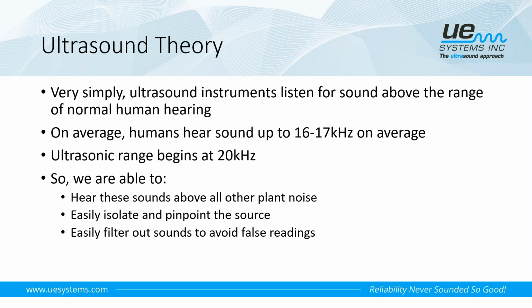And understanding the physics of sound and how sound waves travel will help you to make better use of your ultrasound tool. One of the things that we always stress and teach is the fact that high frequency sound has a tendency to bounce and reflect off of solid surfaces. So if we're pointing the instrument at the floor, for instance, and we're hearing the sound of an air leak, we know that can't be correct because there's no compressed air lines on the floor. So we lower that sensitivity, and that is a way to, again, narrow down the field of view to help block out and filter out those types of sounds to where we can avoid getting false readings with our instrument.